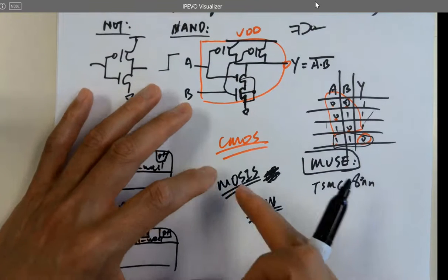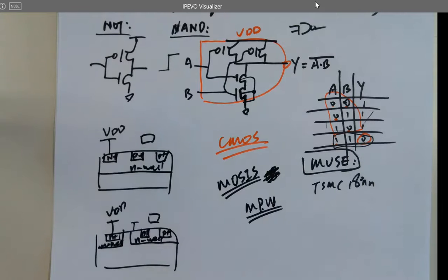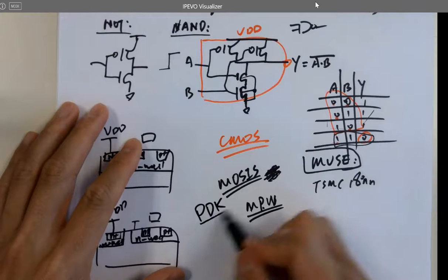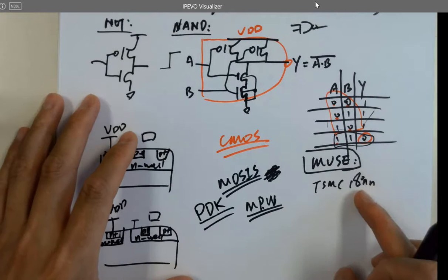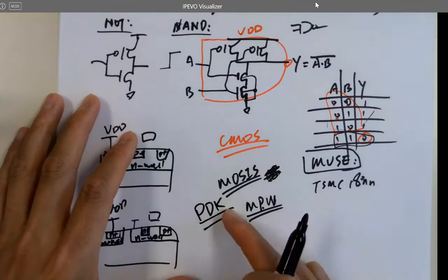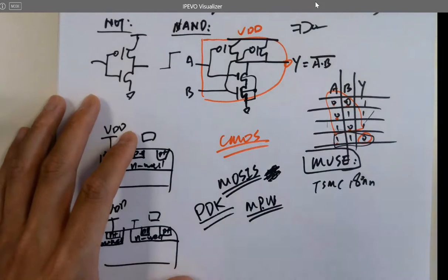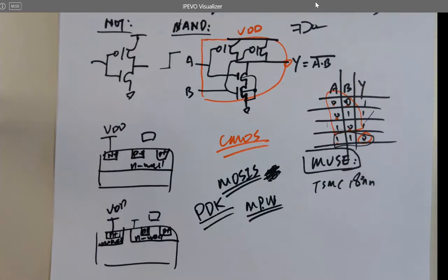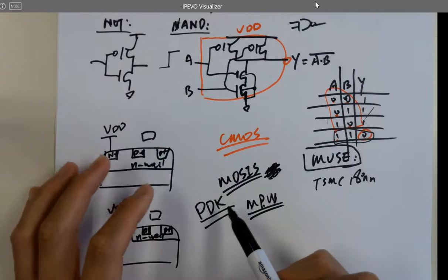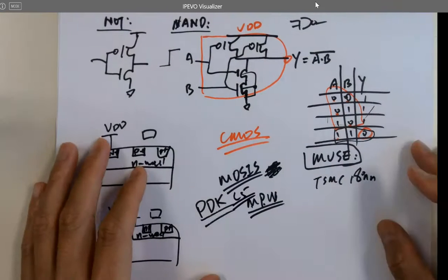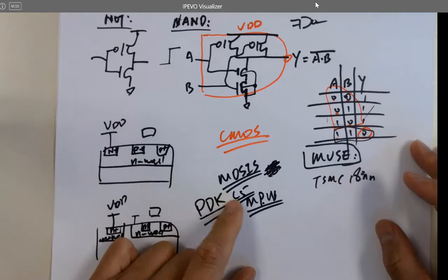It's usually C5, but a lot of times if you want newer technology, just request a PDK, the process design kit. I think pretty much for everyone, not just C5. You request it, you install it on the local server, and you're able to do a design and fabricate it through MOSIS. You have to apply for a grant, but you're not actually getting any money, they will just tape out the chip for you. It's not functioning anymore. For C5, I think the lowest cost to fabricate any C5 chip is $27K, 500 nanometer technology.